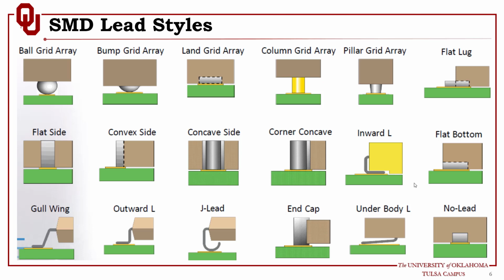So when it comes to SMD lead styles, there are a lot of different lead styles for SMD, but these are the most widely used styles, as you can see in here. And when it comes to the land pattern, it will follow the lead style defined in the data sheet. So you always need to go back to the data sheet and look at the recommendation for a land pattern for a specific lead style. So the lead style is what is on the footprint, and the land pattern will follow that lead style all the time. So you will see all of these.